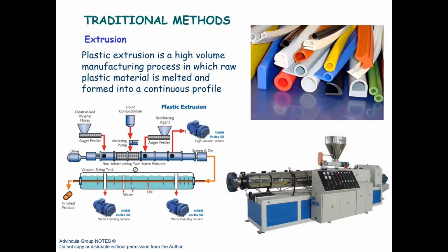So extrusion, injection molding, and blown film molding are ways that plastics can be processed into objects or pipes or different types of consumer goods. And the advantage is that the die or the mold can be produced, and that will allow production at a high throughput. Also, this type of polymer production is based on monoliths. They're not made layer by layer, but they're simply molded, injected, and the object is derived from the melt polymer.